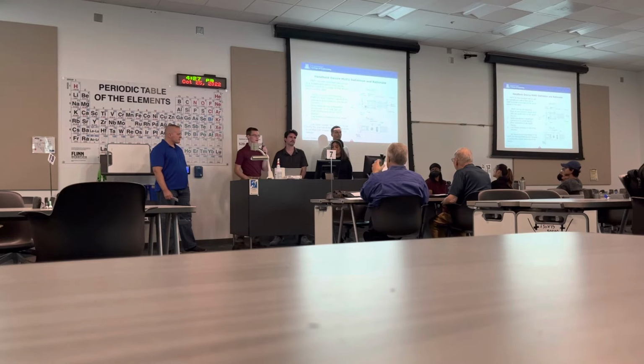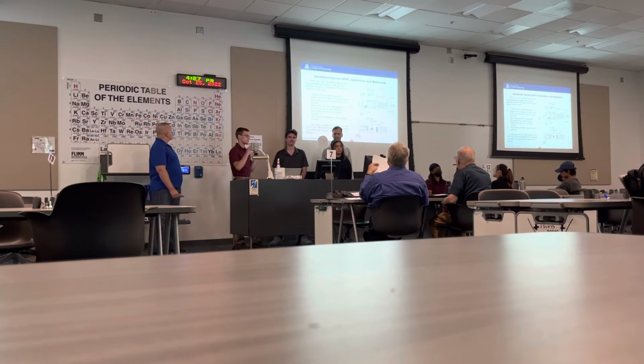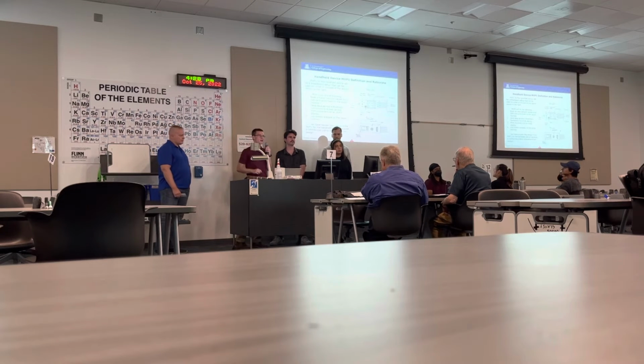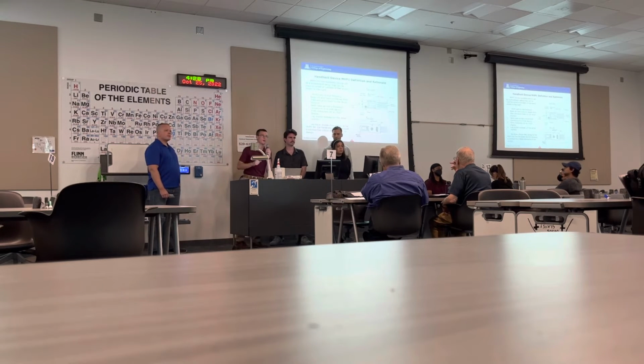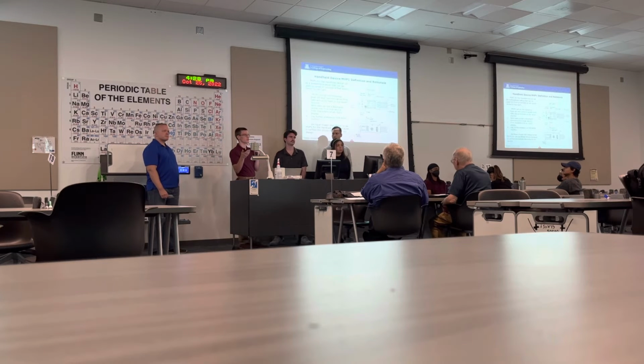So for the handheld device, for MVP1, we're just going to be using a breadboard setup to verify the conceptual layout that you see there on the right. It will be able to do the following. It will be able to read pH and calcium values from the ion selective electrodes and print them to the serial monitor. It will be able to send Bluetooth data across a connection to a host device. It will be able to print characters to an OLED display and log button presses on the serial monitor.